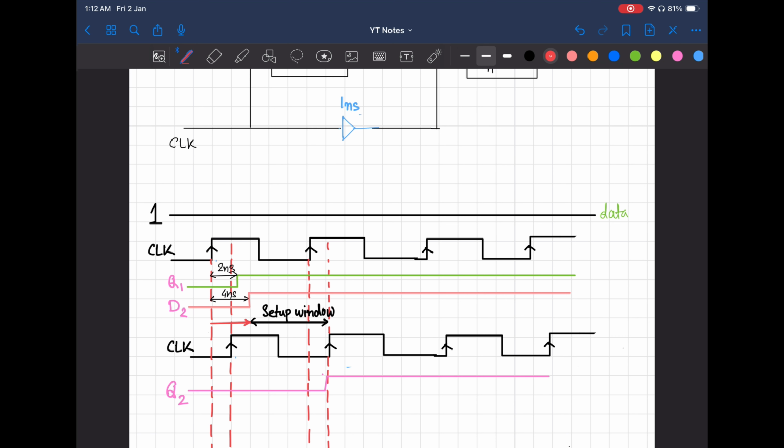as a hold. But there is a catch. You can say this much amount of time is a hold, that my hold is less than or equal to 4 nanosecond. But your hold time is getting worse. Why? Because this clock edge and this clock edge are not exactly at the same point.